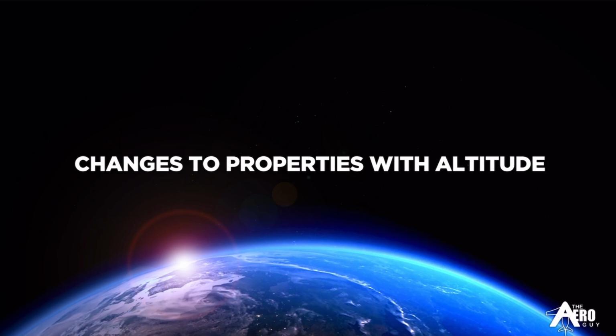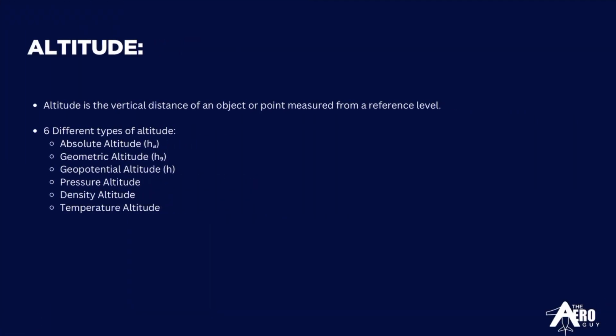But what is altitude in the first place? Altitude is defined as the vertical distance of an object or point measured from a reference level. Because of this definition, we have different types of altitudes depending on where that reference level is. We have 6 main types of altitude: the absolute altitude, geometric altitude, the geopotential altitude, and the performance-related altitudes, which are your pressure altitude, density altitude, and temperature altitude.